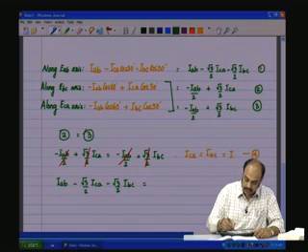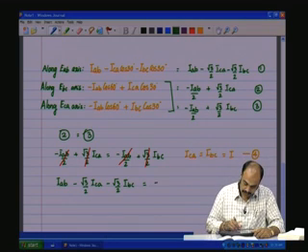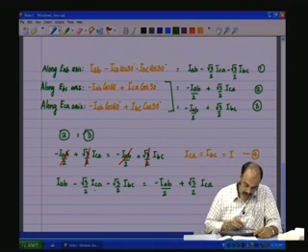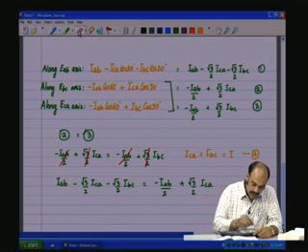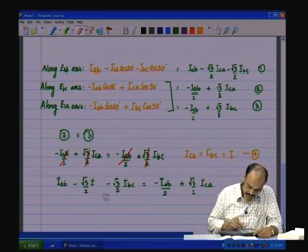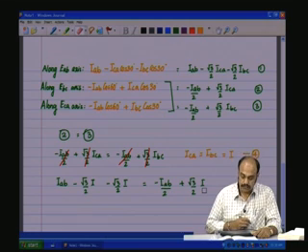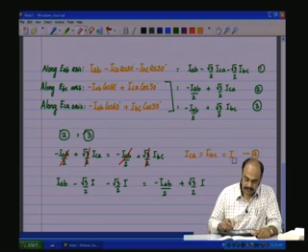So, let us say it is equal to the second, minus I_AB by 2 plus root 3 by 2 I_CA. So, we know that I_CA equals I_BC equals I. So, we make that change, and we have substituted I in the equation.